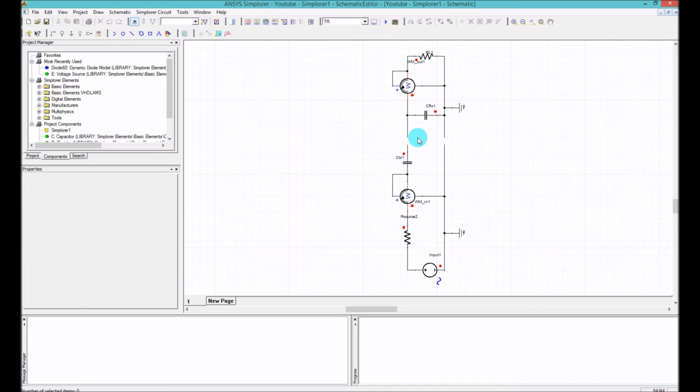If you want maximum power delivered to the TX, you want a resonance LC in series, so you have maximum current going through the L, instead of having it in parallel, which gives you zero current in. For the receiver side, you want it in parallel, so you have maximum voltage dropped on the resistor. If you have it in series, you would get all the current between the L and the C, and you wouldn't deliver anything to the resistor.